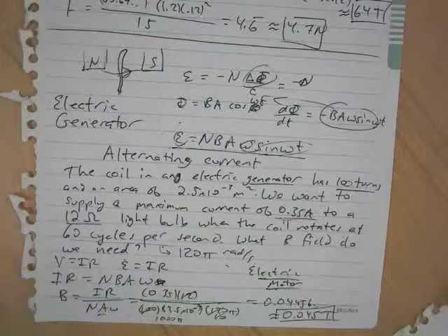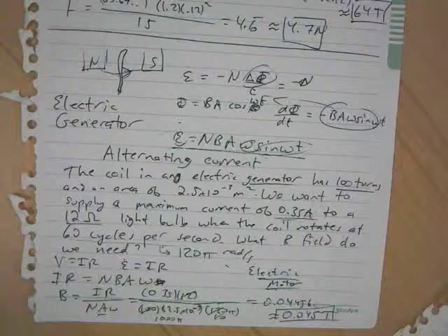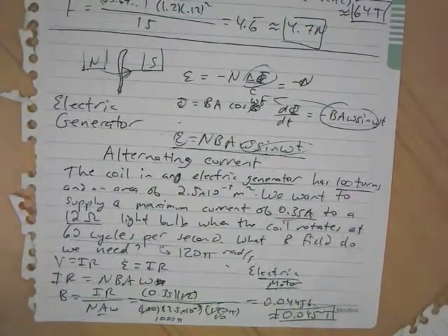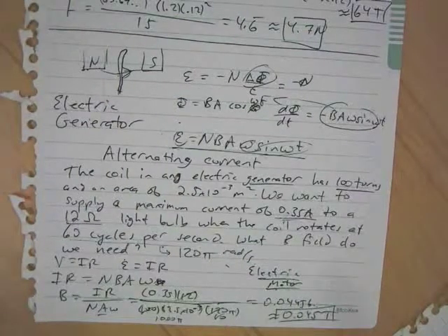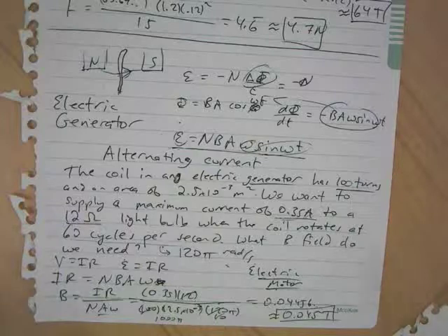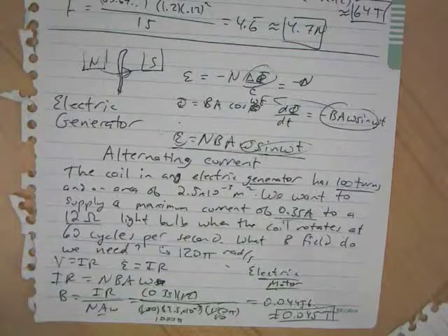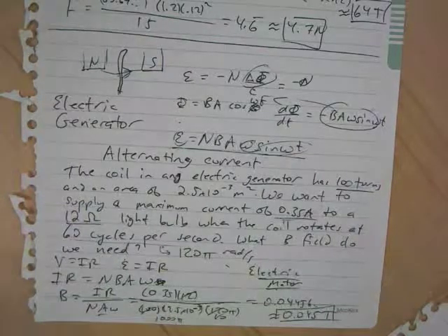But then some of that energy can be recaptured, because when you want to brake, some cars utilize this. Some of that kinetic energy from the wheels turning is then put back into the system, and then that motor takes some of that energy back in as electrical energy and throws it into the battery, instead of it just going into heat, which is what usually happens when you're braking.